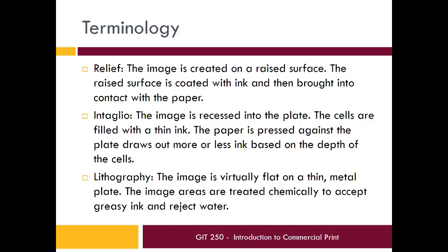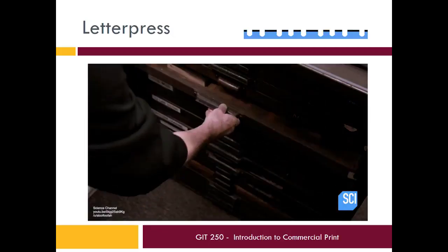Lithography, there are no raised surfaces or indentations or anything. The plate is flat. It is chemically treated so that the image areas will accept greasy ink and reject the water. So lithography operates on the basis of the oil and water repelling each other. And we'll take a look at how that works in a minute here too. But relief, intaglio, and lithography, those are the main key things to be aware of as we go along, because everything we're going to talk about, for the most part, falls into one of those three categories.